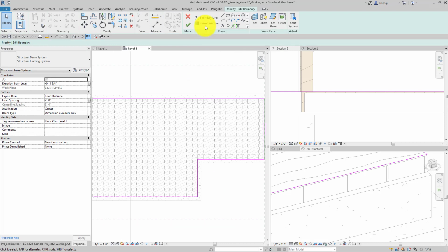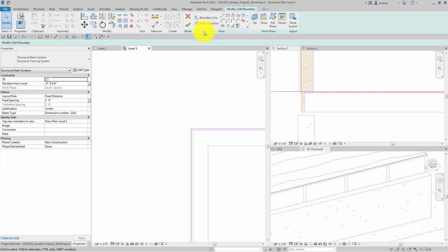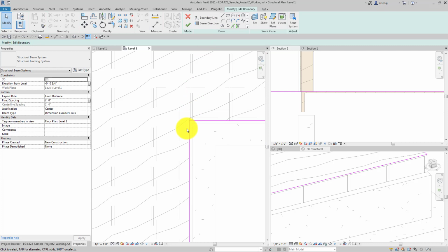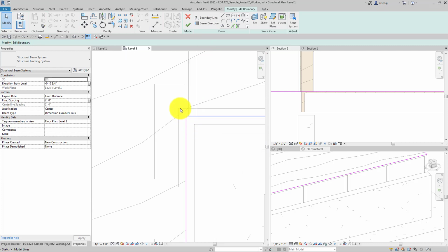And so now we can change the boundaries of this beam. As we can see kind of grayed out here that this is that beam we added, and we can offset this whole chain of beams. We'll want to offset it 1.5 inches, the thickness of that joist. Same thing over here, we don't want it to be copied. We want to hover over, try to hit tab to see if we can get the entire chain of walls.